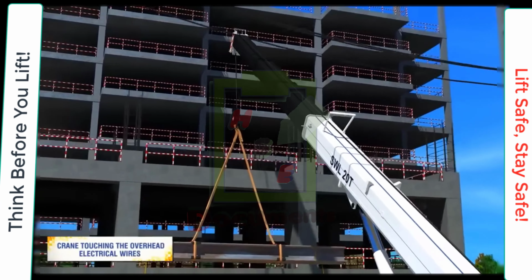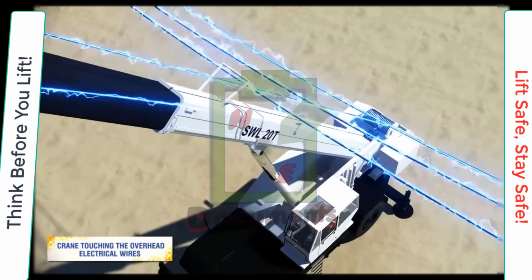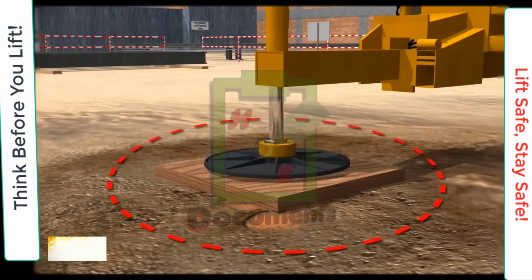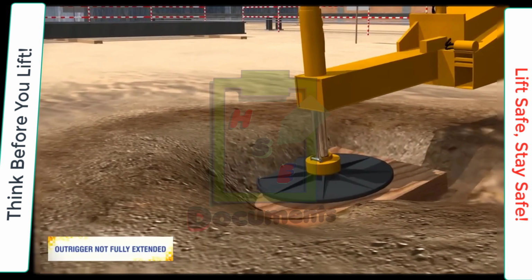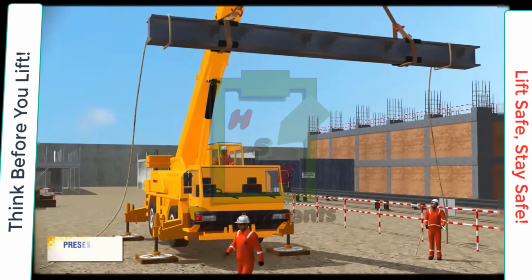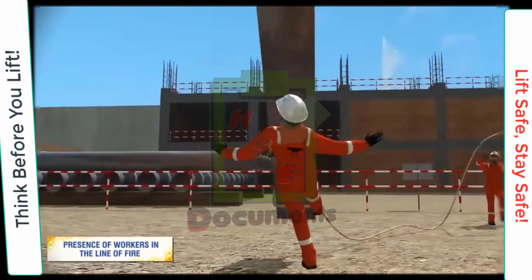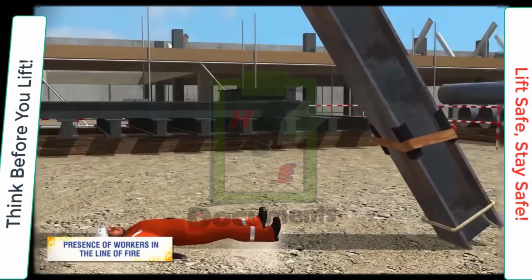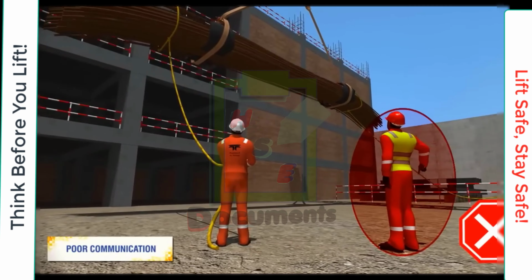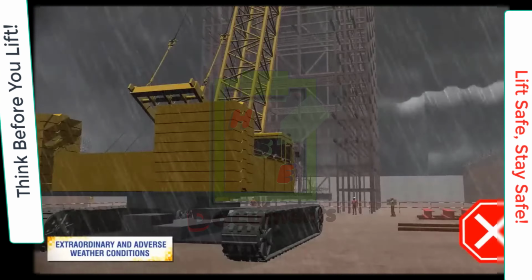Any part of the crane touching the overhead electrical wires, which can result in electrocution. Grounds not being firm and outrigger not fully extended, which may result in tripping, imbalance, or trapping of the crane. Presence of workers in the line of fire. Poor communication between banksman and lifting equipment operator. Using equipment in extraordinary and adverse weather conditions.